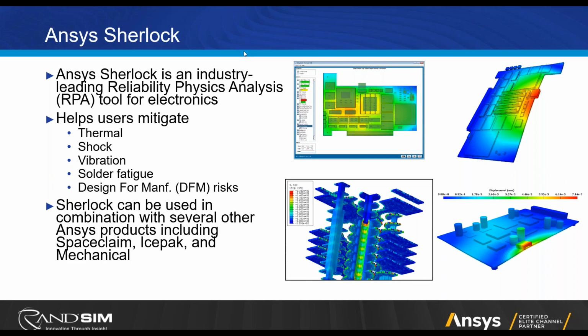This might be portions of your design which aren't manufacturable. They might not have a very good yield. Think of traces that are on the very thinnest edge of what your PCB house can manufacture. Those aren't going to come out as good as, say, fatter ones.